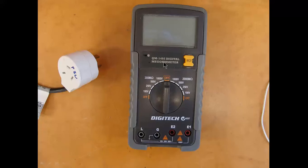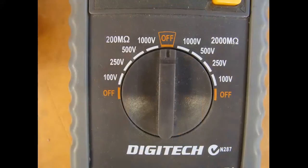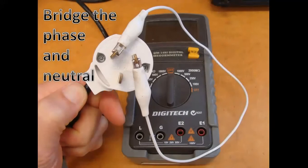So when we use an insulation resistance tester and we have it on 500 volts, what we must do is short out or bridge the phase and neutral connections, and then test between the shorted out connections, phase and neutral, and earth. So by shorting them out, it makes sure that we cannot get a voltage across there. There can only be 0 volts across the phase and neutral.